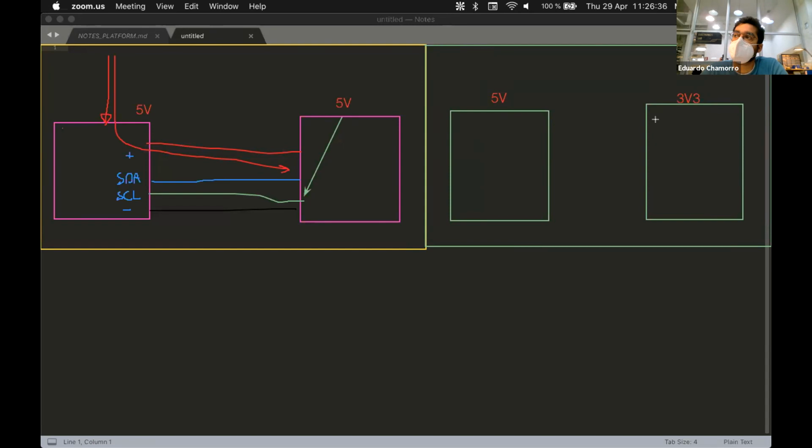For this, we need separate 5 volt communication, and they have the same ground. The 5 volt is not exactly the same voltage, but yeah. That's why you connect the ground together to avoid noise. Okay, so I connect the ground, but maybe one will be 5.2 and the other... No problem.